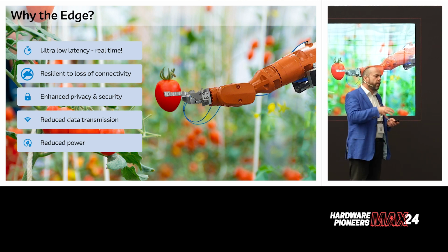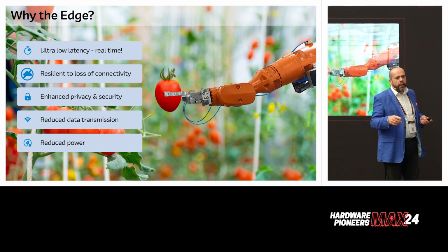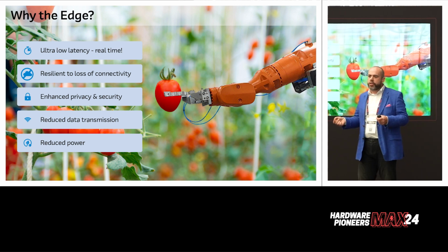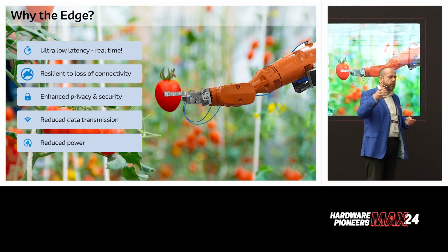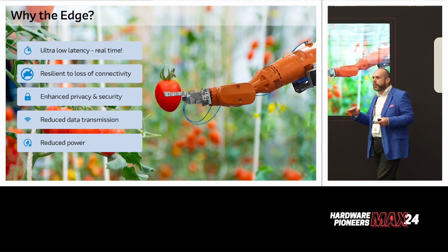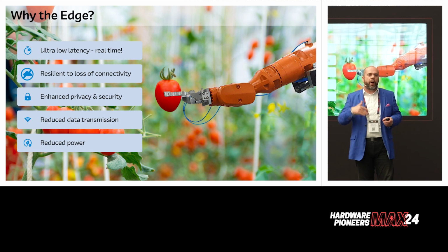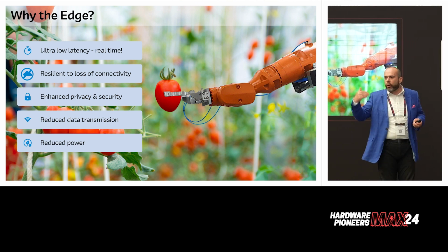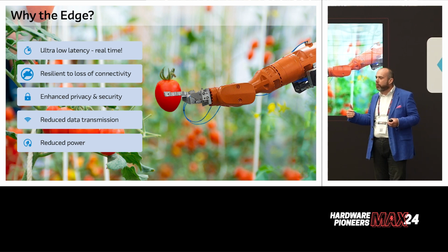If you can reduce the amount of power your device uses day to day, then you can reduce the size of the power regulators. You can reduce the size of the capacitors. You can reduce the amount of thermal cooling it needs. Maybe instead of having a fan, it's totally passive. So just because you're not power limited, always think in terms of saving power. Not just good for the environment, but it also significantly reduces your BOM cost of your final product.